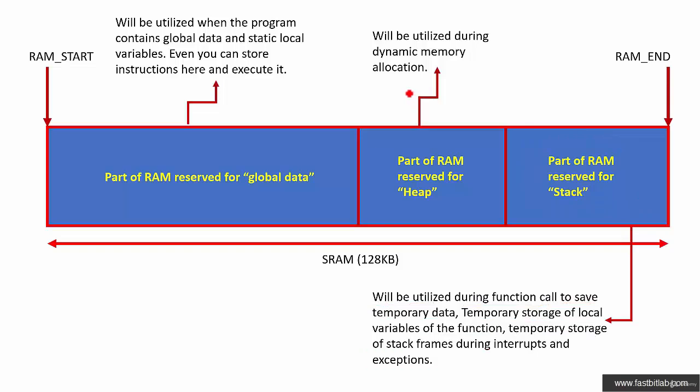You may be having one question: who decides these boundaries? As I said, it is decided by you. You have to do some settings in your program or in your toolchain or in the linker script in order to decide these boundaries. It is completely dependent on your project. I can even move the stack to the front and the global data section to the back. I can shift this heap area to somewhere else in the RAM. I can even do that. This is just one example.